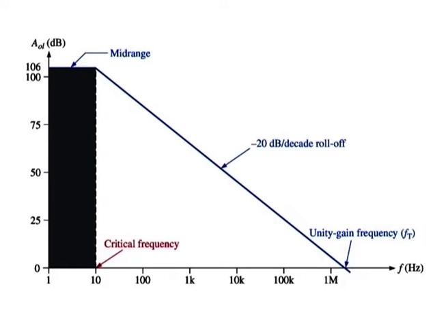Op amps are DC amplifiers as we do not have capacitive couplings between stages and therefore there is no lower critical frequency. This means that the mid-range gain extends down to 0 frequency and DC voltages are amplified the same as mid-range signal frequencies. An open loop response curve for a certain op-amp is shown in the figure here.